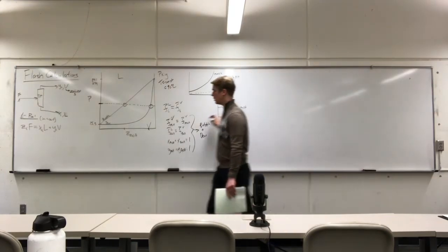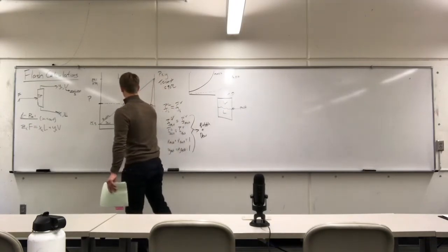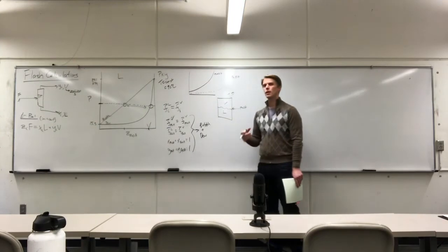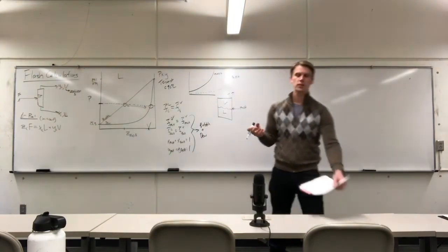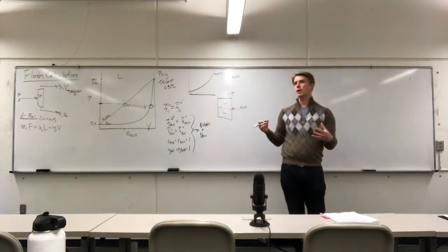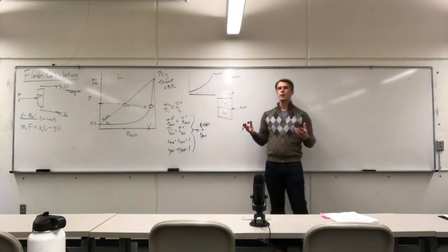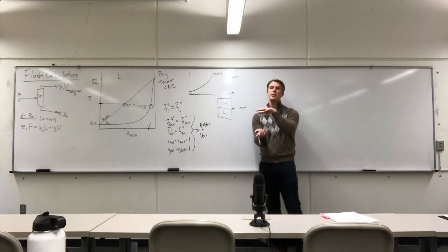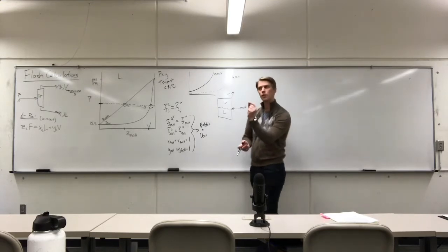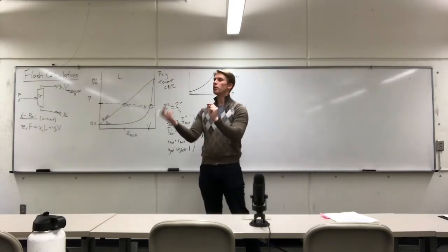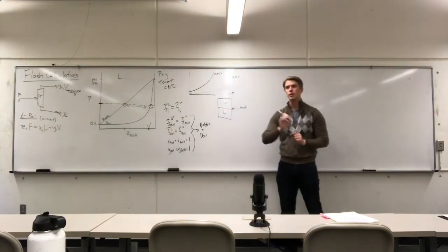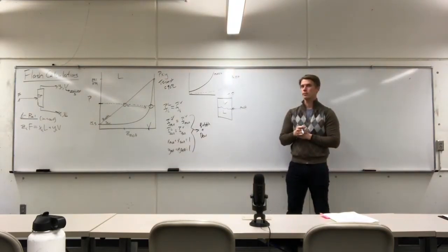I only change how much of each of the two phases I have. Another way to think about this is exactly analogous, if you're doing a liquid-liquid process, oil and water. If I have a container filled with oil and water, there is going to be a finite solubility of the oil in the water phase, and that's only going to be a function of the temperature and pressure. There's going to be a finite solubility of the water in the oil phase, that's only going to be a function of temperature and pressure.